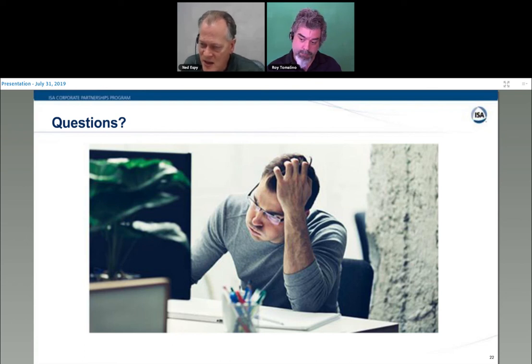This is Leo saying that he has a dual pressure transmitter. If you have a dual pressure system, you've got to calibrate both pressure measurements. It applies to the dual RTD. You almost have to consider it as two devices, even though it's one thing. It's really two functions by the one device, right?